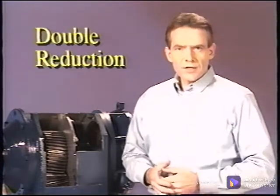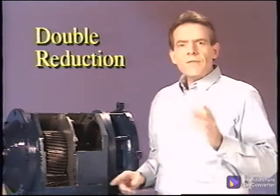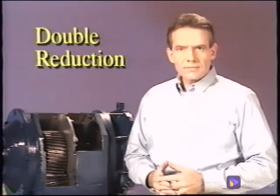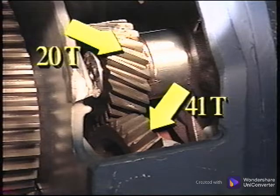The only instance where there is more than 1 gear mesh frequency is in a double or multiple reduction gear drive. That is, the shaft has more than 1 gear, and these gears have a different number of teeth. This gearbox has 20 teeth on the input shaft and meshes with a 41-tooth gear on the intermediate shaft. These two will have the same gear mesh frequency.